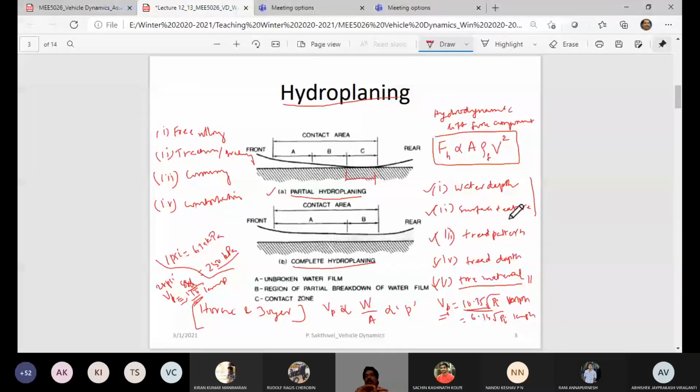So as the tire goes over such a road, the water will be pushed down, and because of smooth macro texture, and because of rough micro texture, there is a protrusion, sharp peaks of your aggregates that would pinch on the tire surface, so it will avoid this phenomenon.